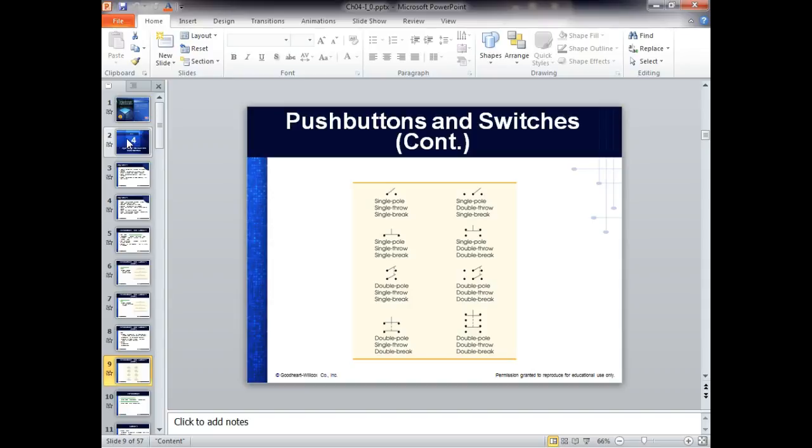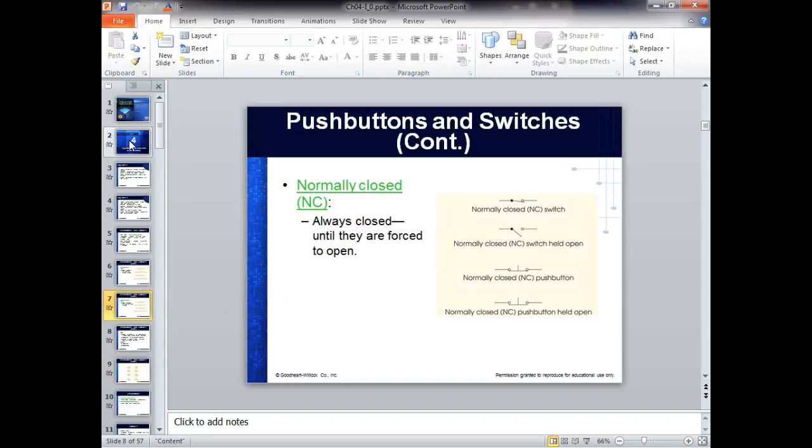It depends. What you do when you hook up, if it's a DC PLC, you buy it. For some reason, Siemens PLCs are normally sinking input and sourcing output, which is used all over the place. Allen Bradley PLCs, since they're used all over the world, give us the ability to select what we want. But they don't give you the ability to select everything.